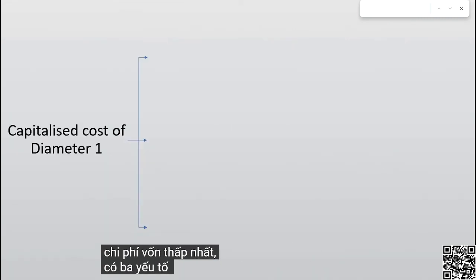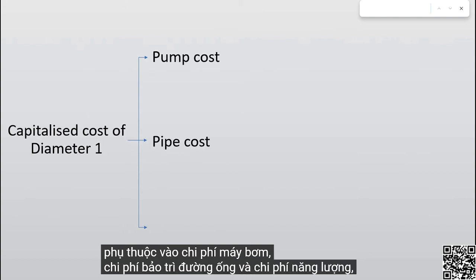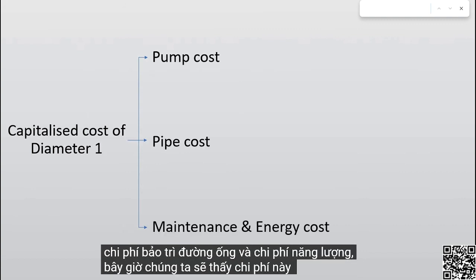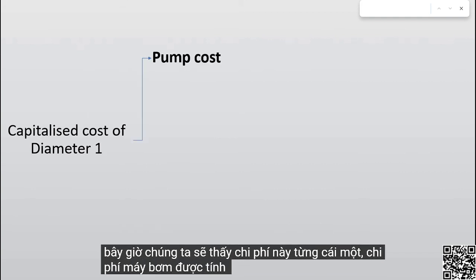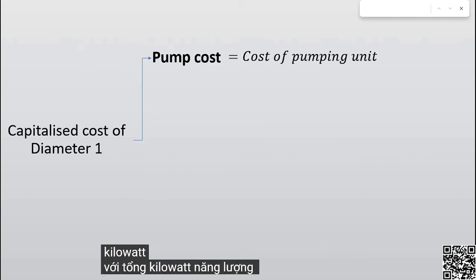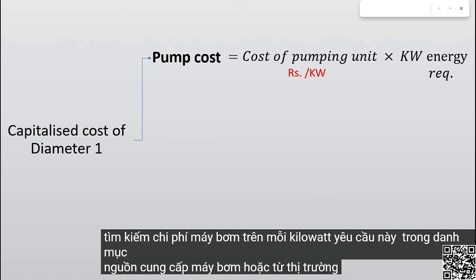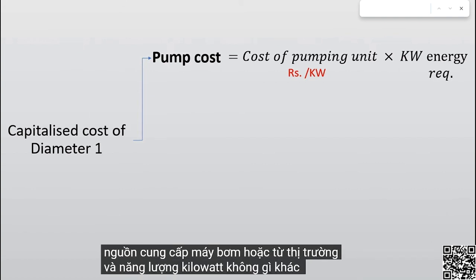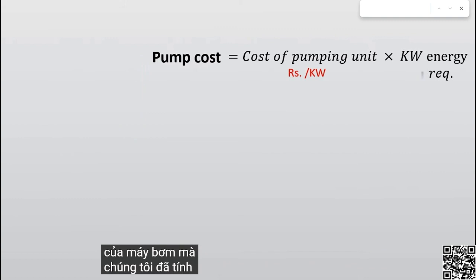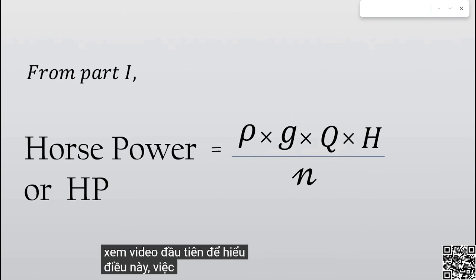There are 3 factors on which the total cost of rising main depends: pump cost, pipe cost, and maintenance and energy cost. Now we will see these one by one. The pump cost is calculated by multiplying the cost of pump unit per kilowatt with the total kilowatt energy required. This cost of pump per kilowatt can be searched in the catalog of pump suppliers or from the market. And kilowatt energy is nothing but the power of the pump we calculated in the previous video. I would suggest watching the first video for understanding this.